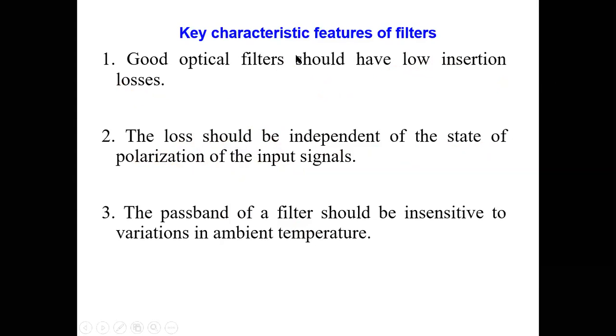Now, since we have studied the polarizations and all, insertion loss, okay. So that's why I told you to write all those points, and these will be the additional points that you will write. So good optical filters should have low insertion loss. The loss should be independent of the state of polarization of the input signal.